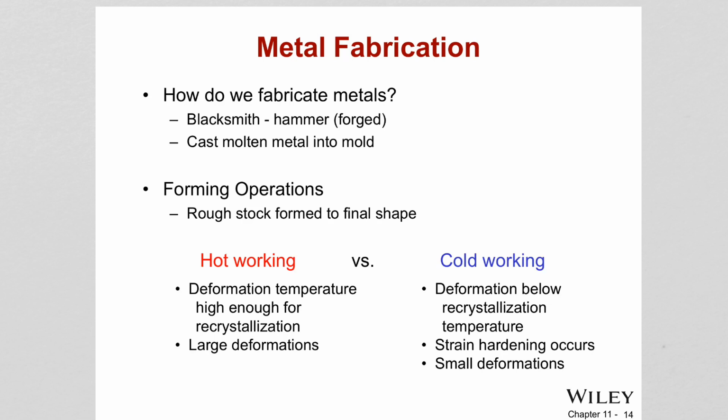And oxide layers are ceramics, basically very hard and brittle particles which can get stuck in the structure after deformation and also provide formation of defects. They can also decrease the surface quality of the part, which might require further processing techniques to enhance the surface quality.